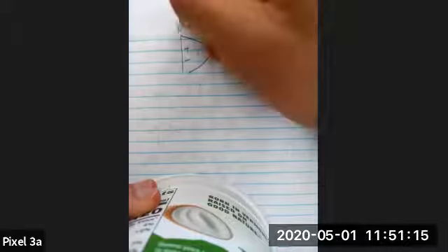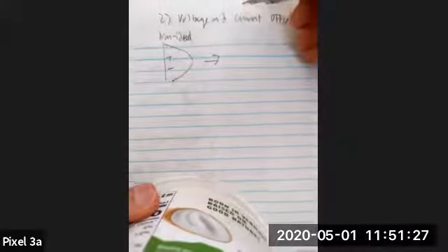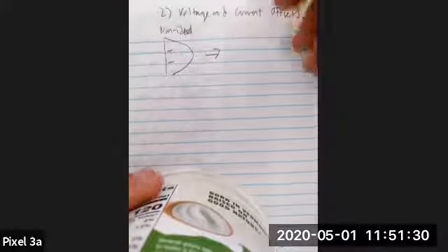So how we model these is that we take our non-ideal op amp, and then we decompose it into non-ideal parts, which are these current and voltage offsets in this case, and an ideal op amp at the end.